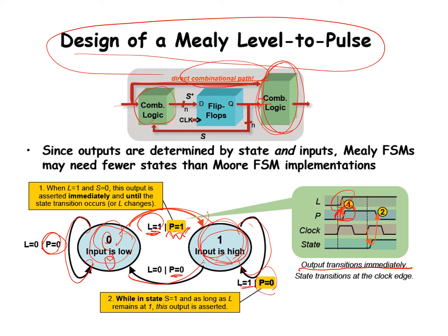If you were to use the Moore machine for any input changes, for example, when the nuclear plant is about to explode, the shutting down of the nuclear plant will happen one cycle later, right? Because after the state transition happens, the output will change, right? So in this kind of emergency situation, you need to use a Mealy machine so that the output is affected immediately, okay?